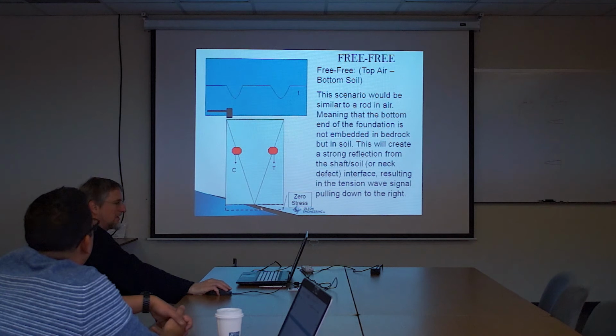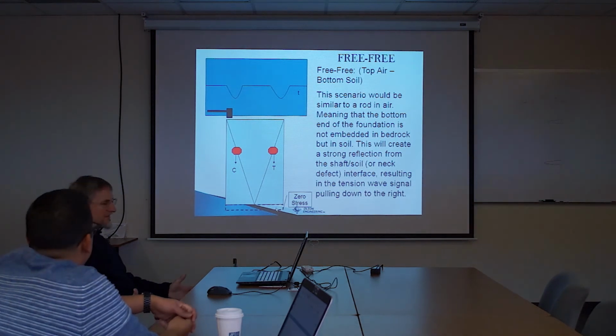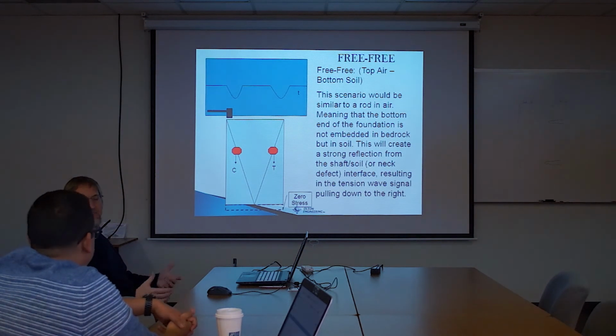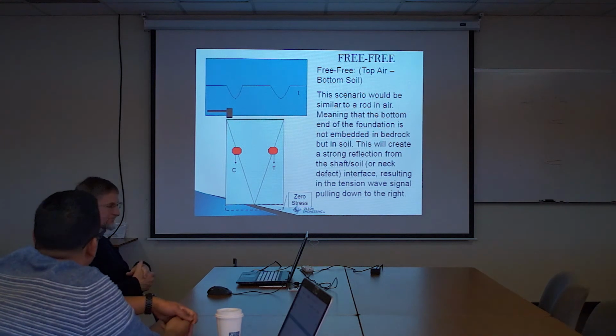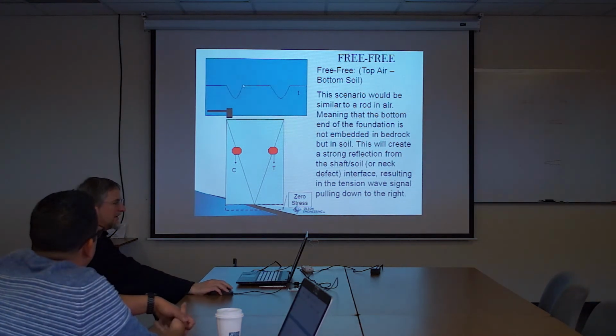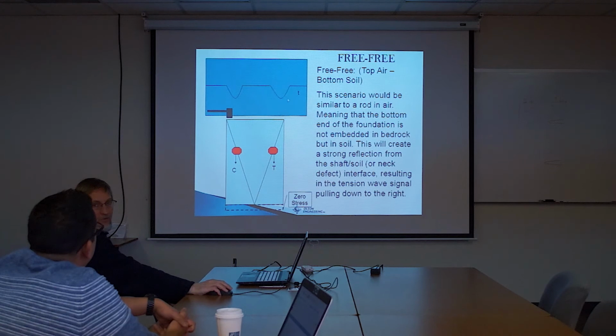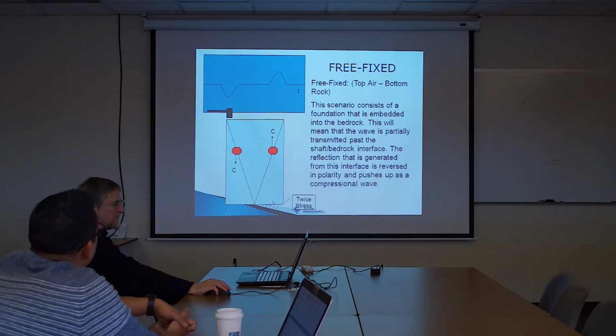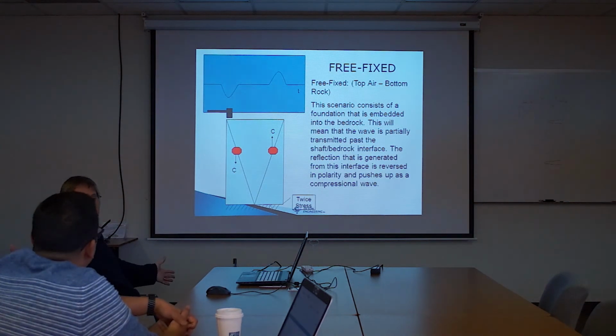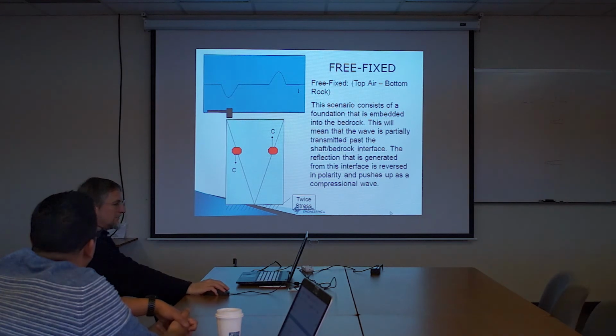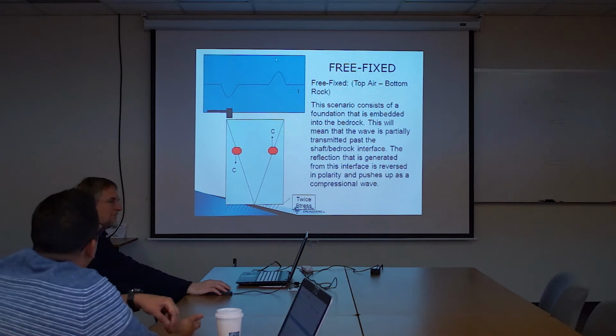Free means the ideal case would be a shaft where the end of it's just in air, something that's less stiff than the concrete. Most soils are less stiff than concrete, in which case you get an initial downward break and your bottom's a downward break. If the bottom is stiffer than concrete, which may be the case with an infinite limestone, then instead of breaking down, it breaks up. It breaks the opposite direction.